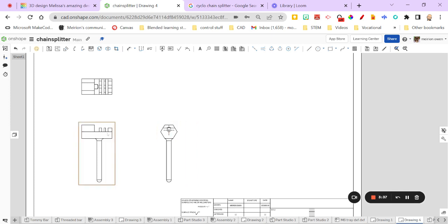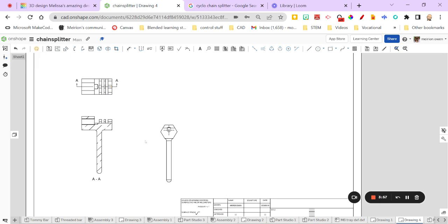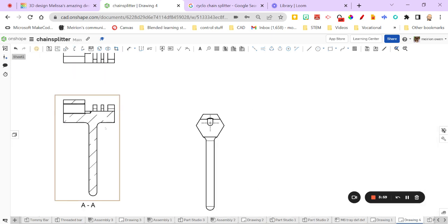And this is going to change in a sec, right? So what's going to happen here, I'm going to delete my front elevation. And I'm going to go up to the top toolbar and I'm going to pick up sectional view. Now in sectional view, I can click to make a horizontal sectional view. And I'm going to click in the middle of my plan. And I'm going to drag down and it's going to create for me a sectional front elevation. There it is, right? Sectional view.